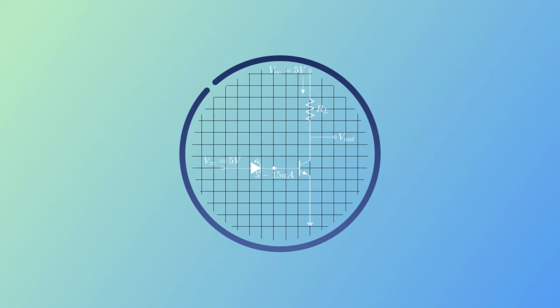For this particular photodiode, the typical output current ranges from 5 to 50 microamp under the range of light intensities. Suppose that 10 microamps is the output for the reference light intensity. We can translate this small base current into a larger collector current using a BJT with a current gain of 100. This collector current will then run through a resistor RL for the voltage to be tapped off.